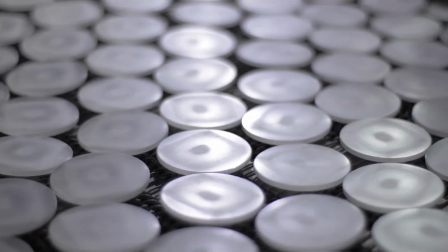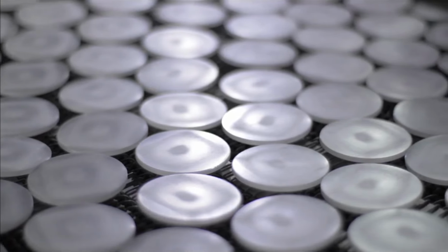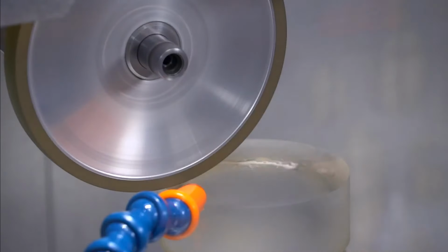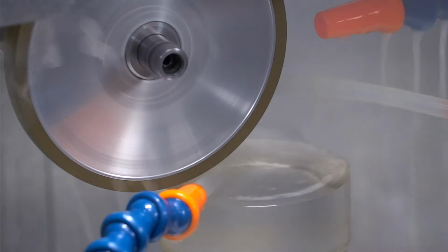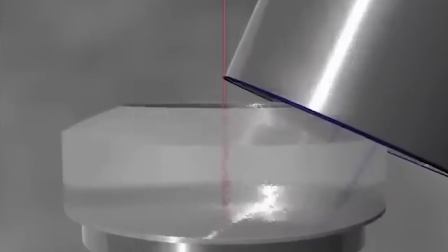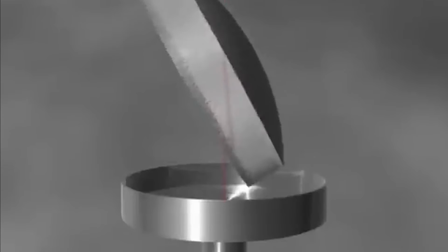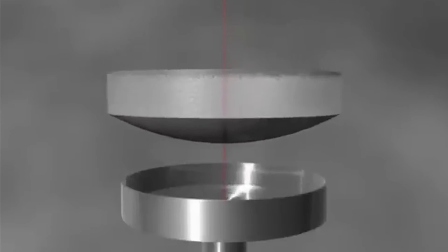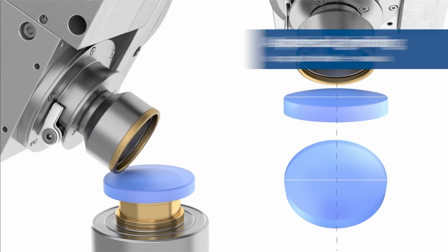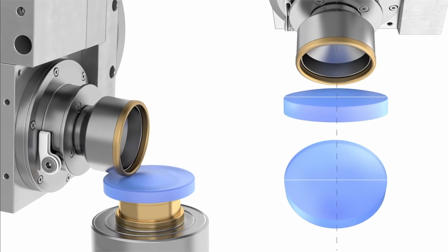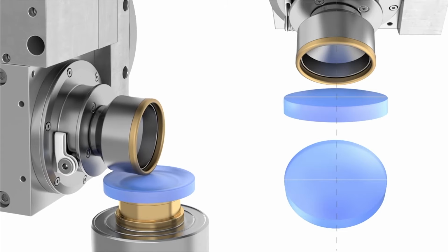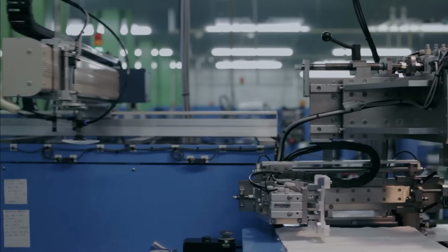Now it must be turned into a clear optical lens. Experts and machines collaborate to accomplish this task. They place a blank glass or glass disc on a revolving device so that a curve generator may grind it precisely. The curve generator has a diamond cutter that uses CNC technology to precisely carve out the lens. To create a blank into a convex lens, it grinds the corners small while keeping the center thick. A concave lens, on the other hand, is created by grinding from the thin center to the thick edges in one continuous motion. This is known as spherical grinding.